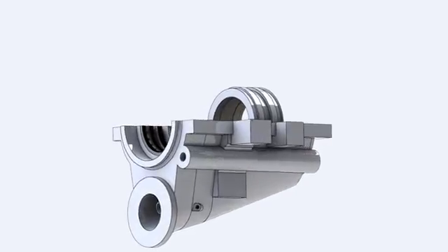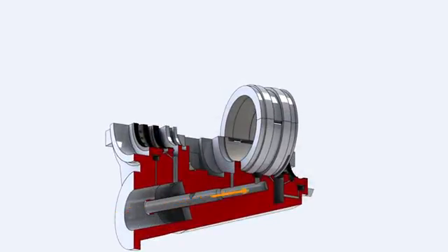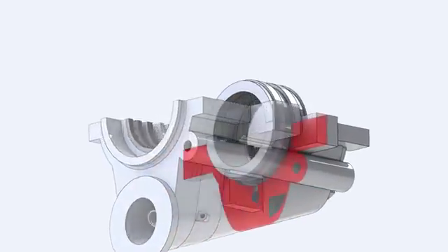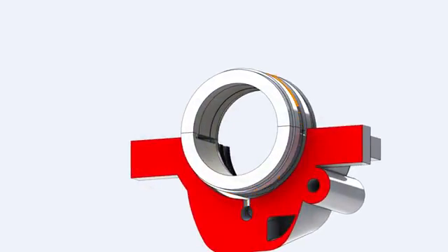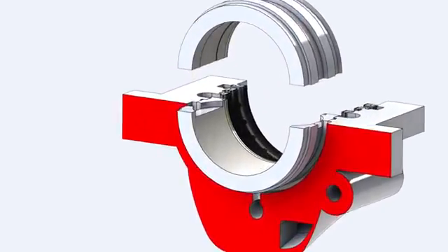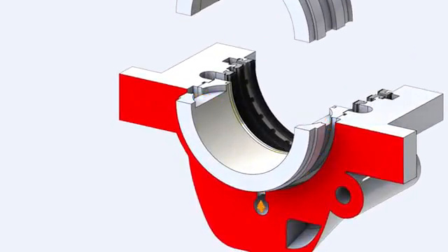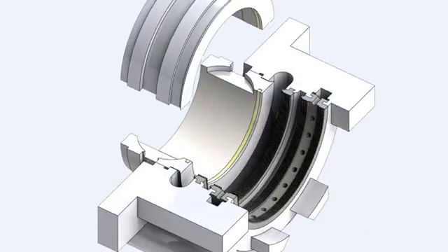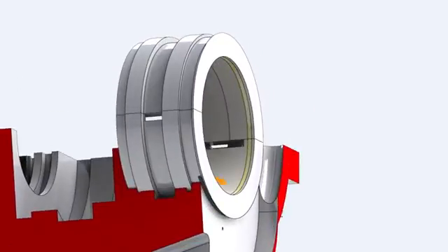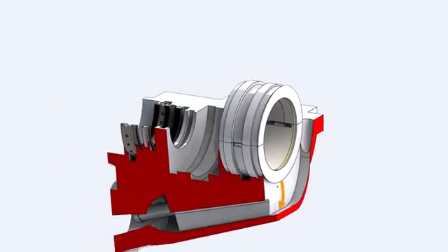For lubrication, oil is supplied through the oil feed pipe to a port in the lower bearing housing, where the oil fills an annular space around the liner and is admitted inside the liner through 2 grooves machined at the horizontal matching edge. Oil is drained through the vertical drain slot at the bottom of the lower liner half to the journal drain cavity down to the oil drain piping.